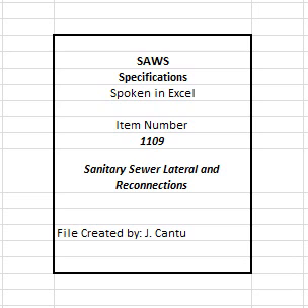E. Embed the lateral pipe and point of connection, as specified for sanitary sewer main, and as shown in the contract documents. F. Place and compact trench zone backfill in compliance with specification item number 804, excavation, trenching and backfill. G. Install a minimum 2-foot length of magnetic locating tape along the axis of the service stub out and 9 to 12 inches above the crown of the pipe, at the end of the stub out.